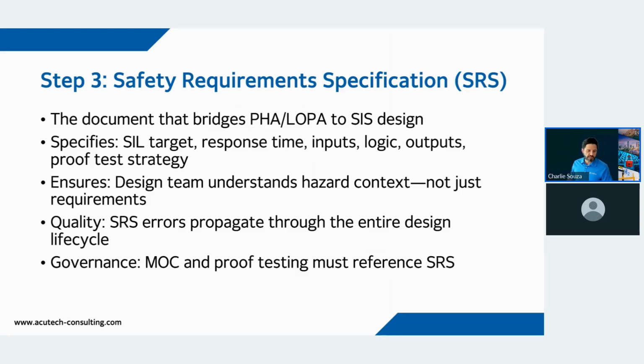We get to step 3. So after we leave LOPA, we go into, okay, we've received this LOPA, PSM wants us to create the safety function or design the safety function. So we start recording those requirements, design requirements, operational requirements, all sorts of requirements based on hardware, software, or even operating conditions, type of service.